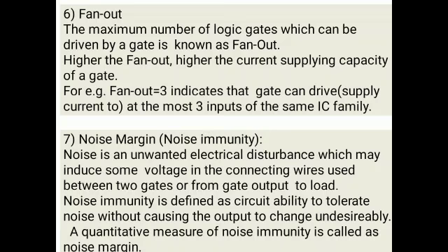So higher is the fan out, higher will be its current supplying capability. If fan out is 3, it indicates that the gate can supply at the most 3 inputs. Means we can connect 3 inputs to a particular gate if its fan out is 3.